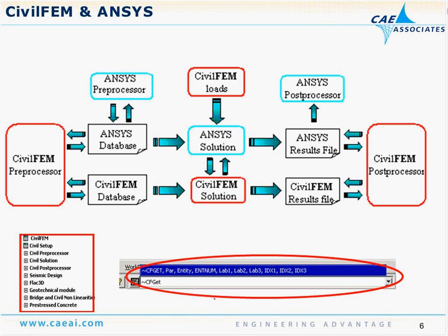CivilFEM is command-driven, similar to ANSYS. So you see in the lower corner of the screen that there is a ~CF get command. All of the CivilFEM capabilities are driven by commands similar to ANSYS, so they can be fully integrated into a solution sequence.